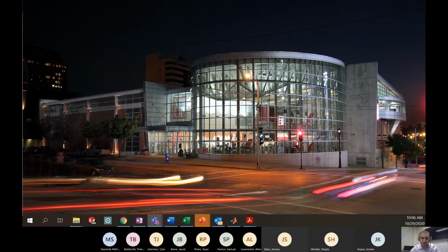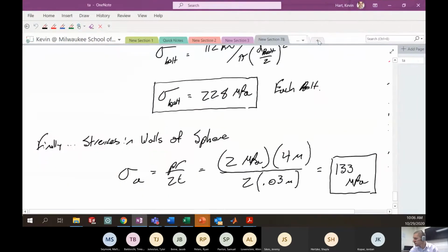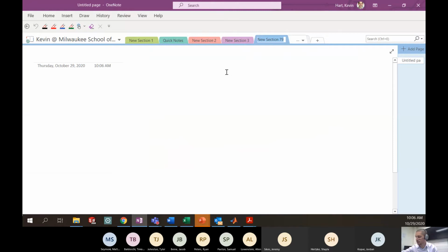Now, let's get into the actual lecture material itself. We've got to talk about some of these techniques that we're going to use with these strain gauges, which we haven't really talked about before, because we're going to use strain gauges in a new way to isolate effects of just the shear stress that might come from torsion. So today we're going to talk about advanced strain gauge techniques, and specifically how to isolate effects of just torsion. So advanced strain gauge techniques.